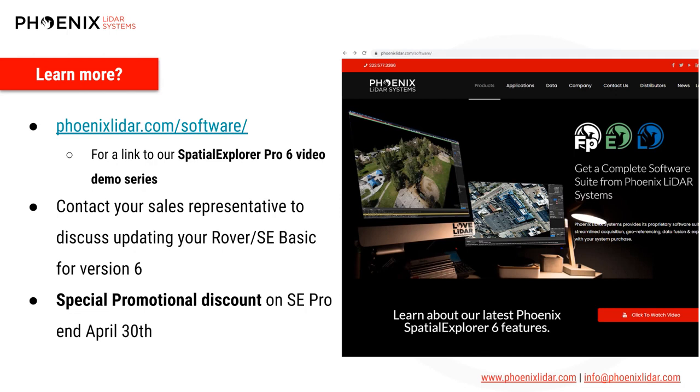All right, we do have a few questions here. The first one, and I think Conrad, you can, or Ben, you can address this. Will this take away the need for Inertial Explorer? And I think that's probably a question that a lot of people have. So SE Pro integrates with LiDAR mill to compute trajectories. So yes, if you have a valid LiDAR mill subscription, then you no longer need Inertial Explorer to do trajectory post-processing.